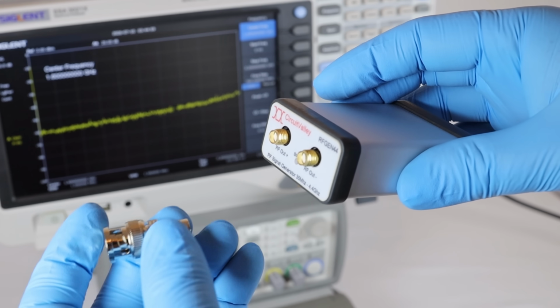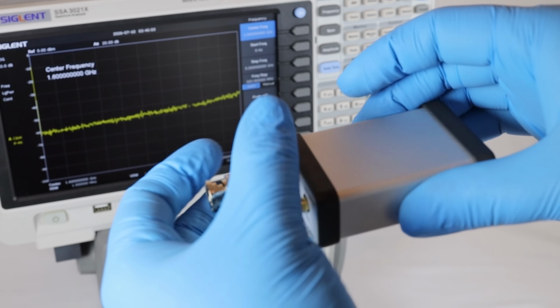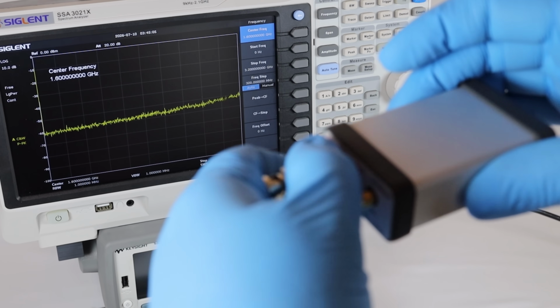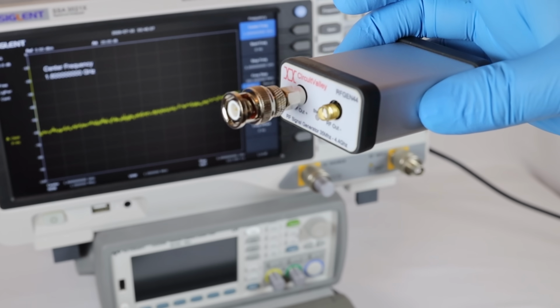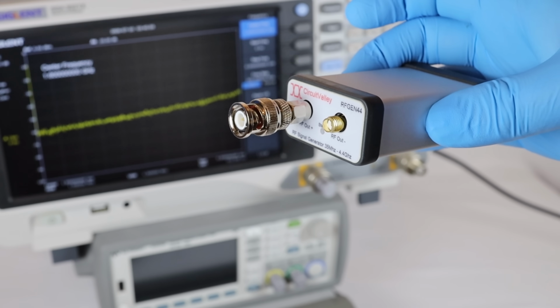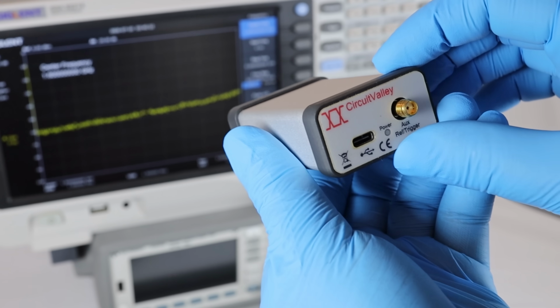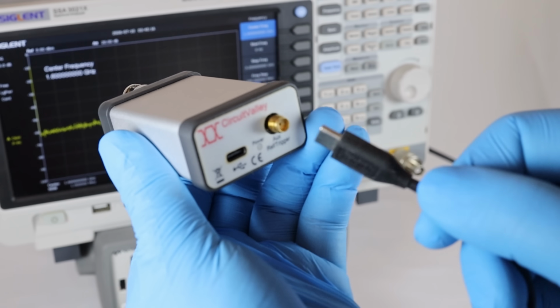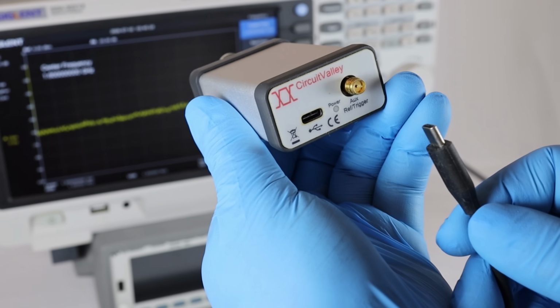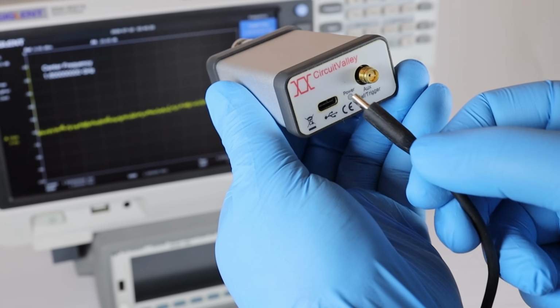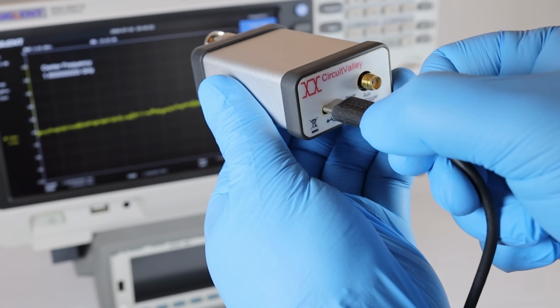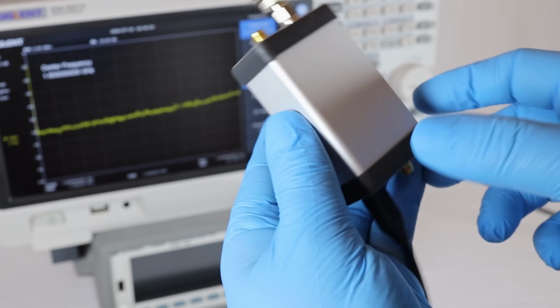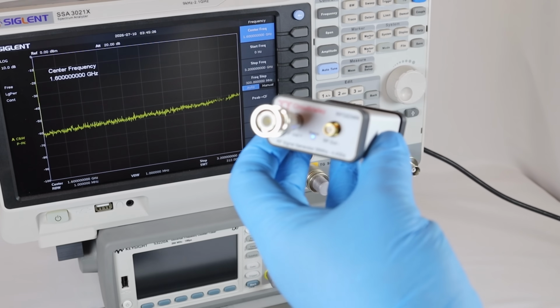This is a highly compact unit, small form factor, with two RF source outputs on the front, USB-C and aux IO on the back. There are status LEDs both in front and back. The aux port can also be used for external reference, internal reference, and as sync IO. The device supports standalone operation without needing a PC. If it is programmed, you will immediately see an RF signal as soon as the device is plugged in. We are using an SMA to BNC adapter to plug into the BNC input of my spectrum analyzer.